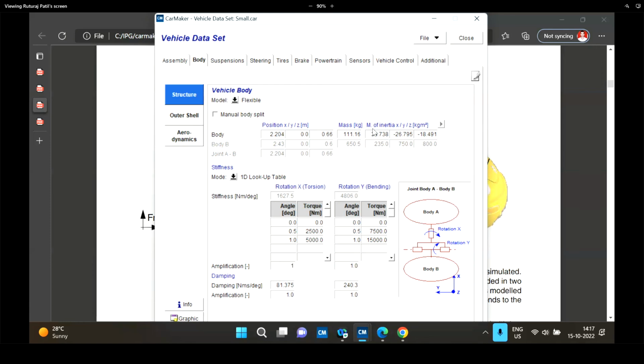In case of the EVA team, you can leave the engine weight as 0 in the assembly tab, but in the body tab, you have to adjust your battery as well as your motor package weight. If those are grayed out there, you have to adjust it in the mass and changes field, which is shown where the pointer is currently pointing. I hope that is clear.